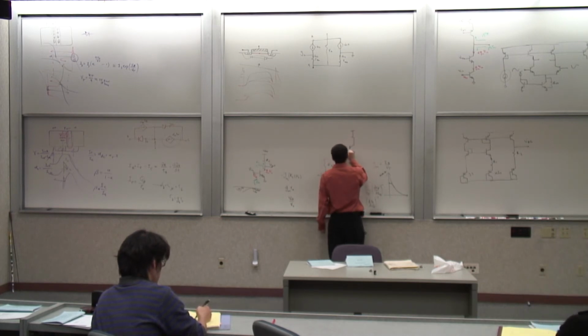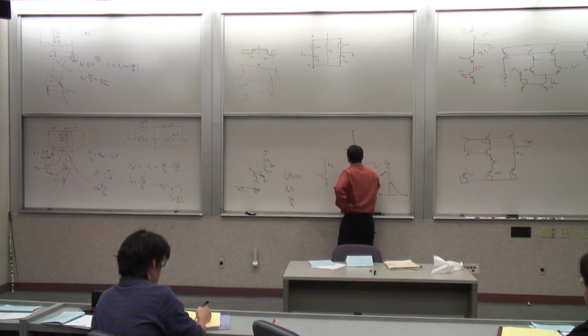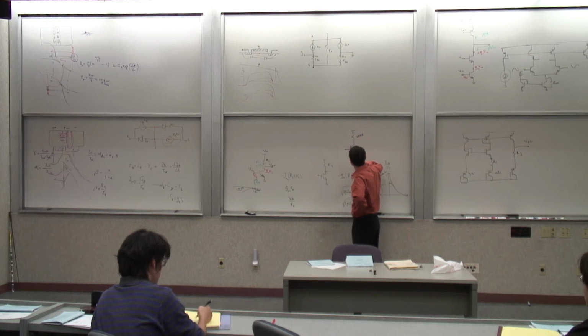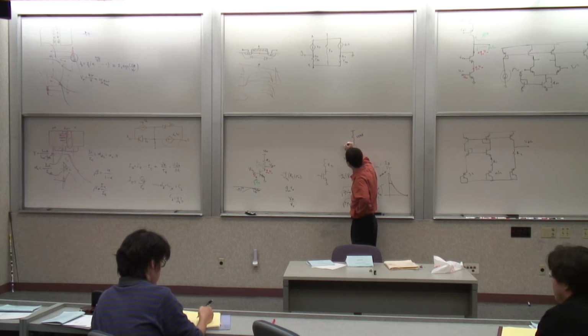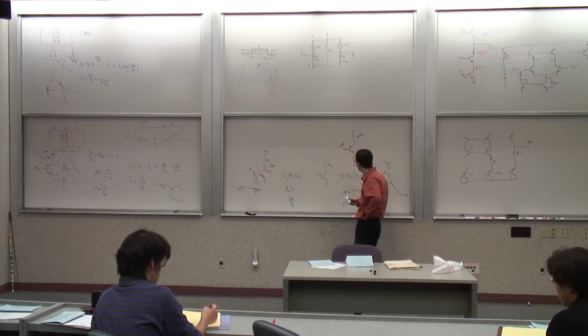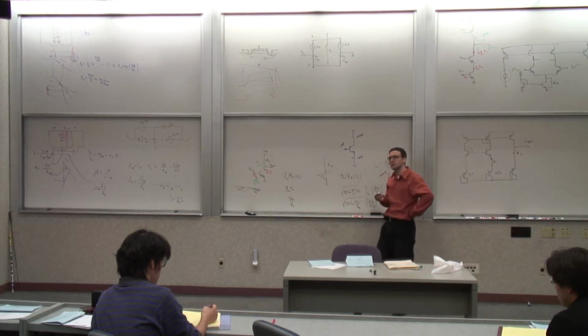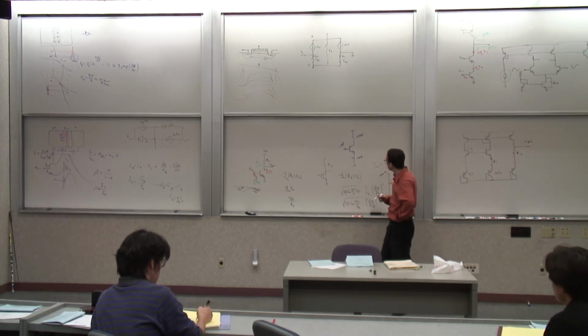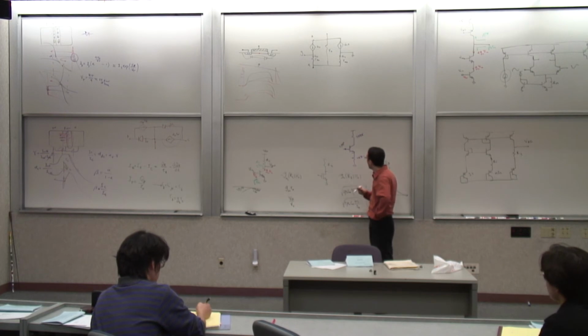Let's say if we take this one, and I say to you that this is the 100 kilo ohm resistor and this is a 1 kilo ohm resistor, and I set this DC level voltage to, let's say, 1.7 volts, DC wise, somehow. I'm oversimplifying. So, what is this transistor? What mode of operation? Let's say I assume that it's in forward active region.